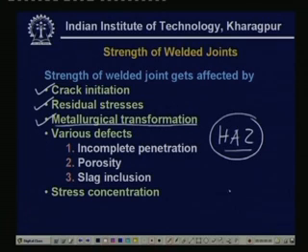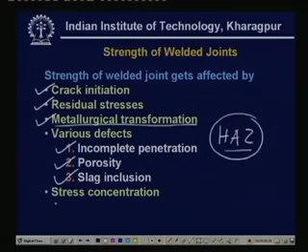There may be various defects possible, because welding could be considered a solidification or casting process. All the defects present in the casting process will be present in welding as well. So there may be incomplete penetration, there may be porosity, and there may be slag inclusions or foreign element inclusions, which may also reduce the strength of the joint. And last but not the least, the stress concentrations. There may be some regions where the stress may be concentrated. So this will lead to failure if proper care is not taken.